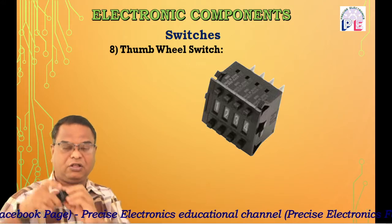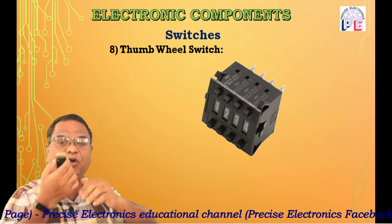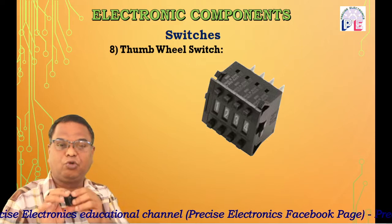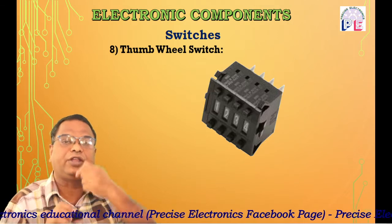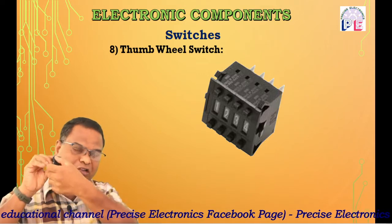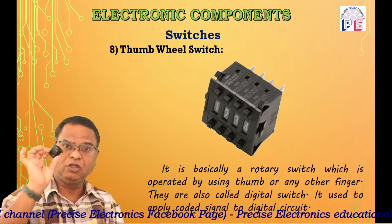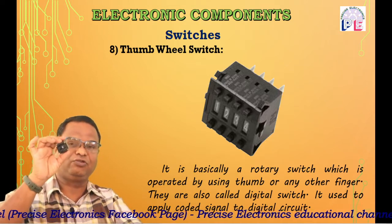Suppose there is number 1, the number 1 is displayed. So the output of this switch is the corresponding binary number of the applied decimal number. So that is coded form. The thumb wheel switch is mostly used in digital devices to apply coded information to the instruments, and it is a rotary switch. By using the thumb, we change the position of the switch. So it is known as a thumb wheel switch, which is used in digital devices. It is also known as a digital switch. So friends, that is the thumb wheel switch.